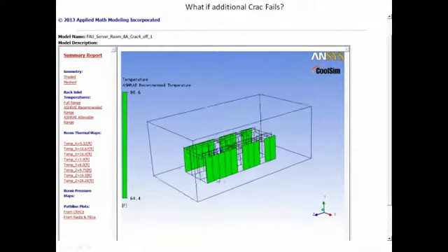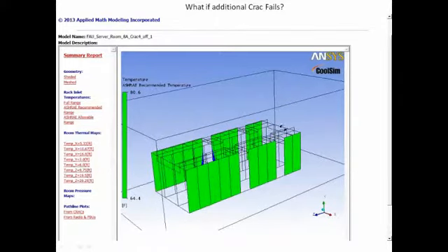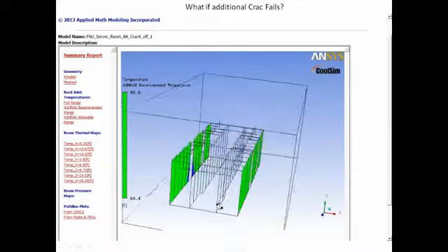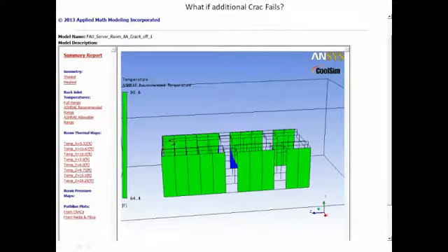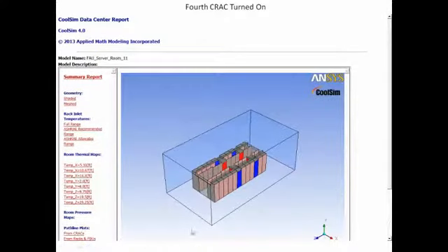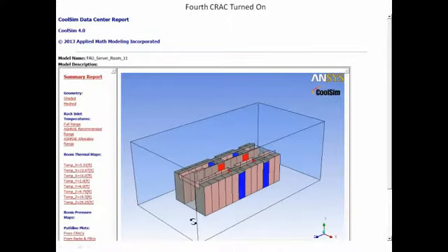Now, in this particular model, let's take a look and see if they conformed, and they do. You see, if you pull the containment off the top here, then the model actually will conform to the ASHRAE spec and it will be okay. But you have to know that that's necessary. And you wouldn't know it if you didn't somehow run a model or study the detail a little bit more than is often done.